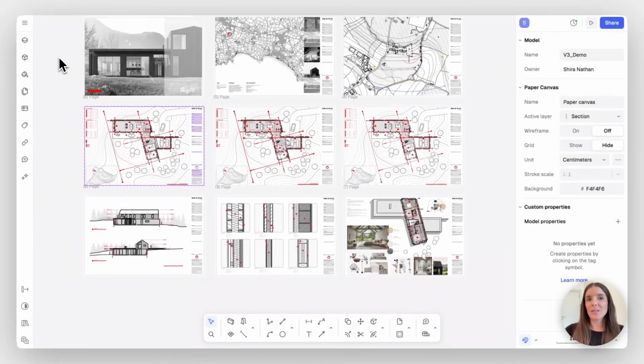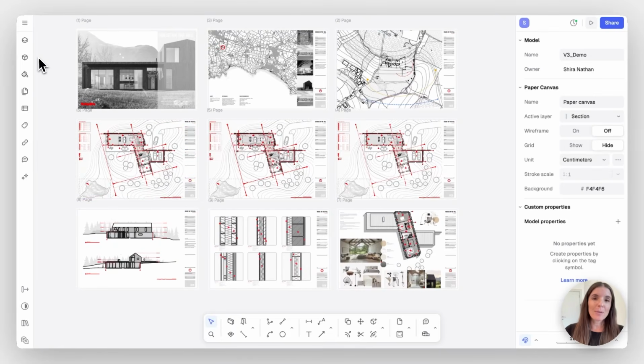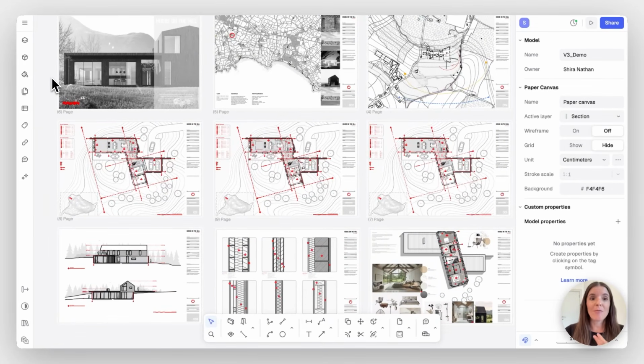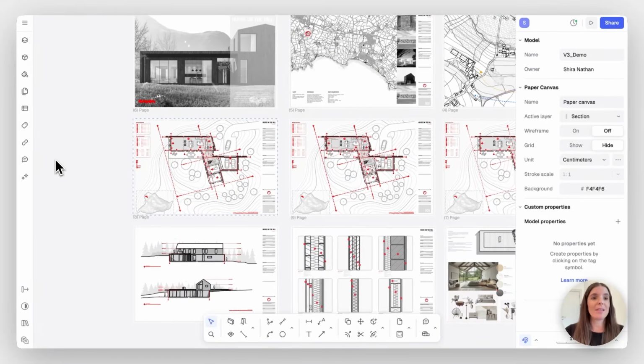Basically, you can usually start with either importing a file. DWG, DXF, PDF, or images are all supported within Rayon and can then be edited super flexibly. So if you're bringing in a PDF, it's going to become vector lines that you can edit. If you're bringing in a DWG, it will inherit the DWG layers and CAD blocks. So really ready to go and to redesign in Rayon.